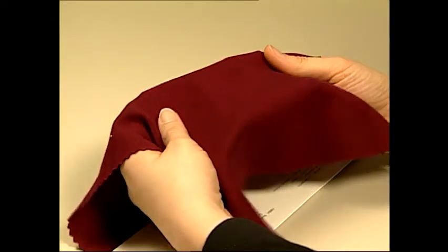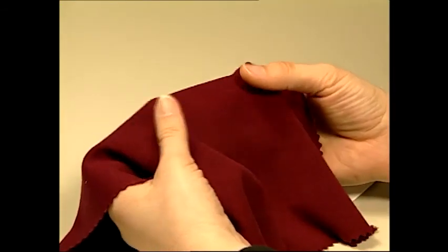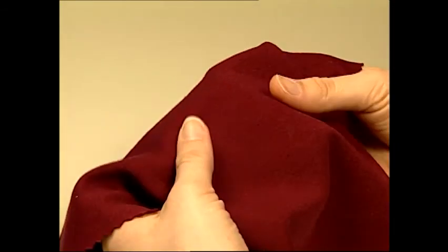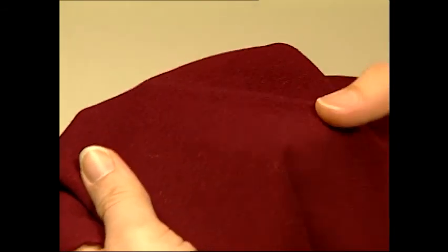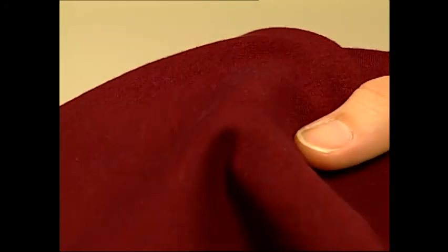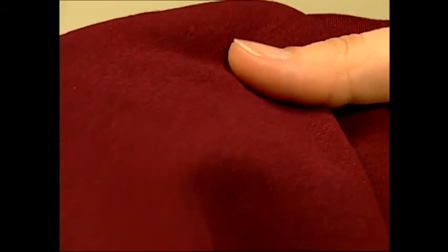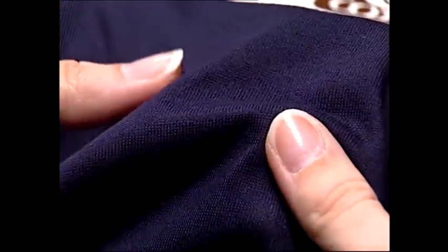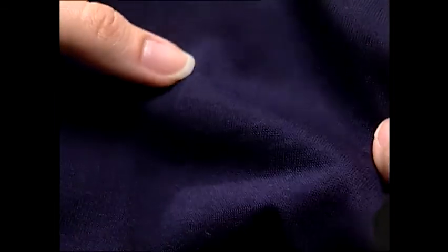Fabric construction has an impact on the shrinking characteristics of a fabric. For example, the performance of a single piqué is certainly different from that of a single jersey or interlock made from the same yarns. Each has different construction parameters and will deliver different specifications of weight, width, and shrinkage. Important construction variables include yarn, machine gauge, machine diameter, stitch length, and the type of stitch used.